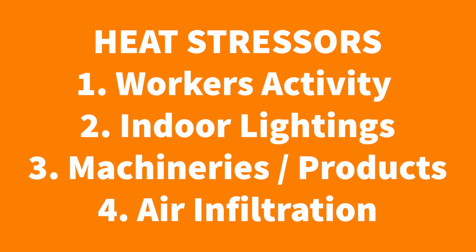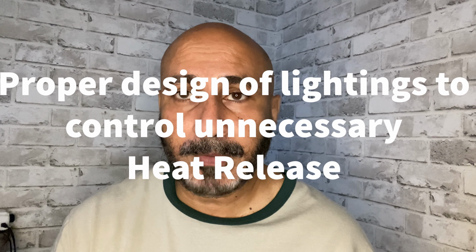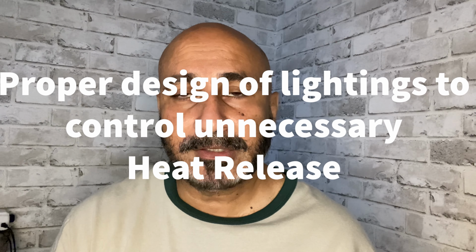Then we have lights. Lights are another significant source of heat. The type of light you're using depends on your job scope or on the requirement in that particular room, the lux required, if it is a room where it requires the usage of light. If it's a reading room, or a library, or a storeroom where you're going to come and pick up products from time to time, light is going to play an important role. It's going to be a task-based illuminance requirement. So all this has to be finalized first. Then only you can narrow down the amount of heat that is going to be generated internally from that particular room.